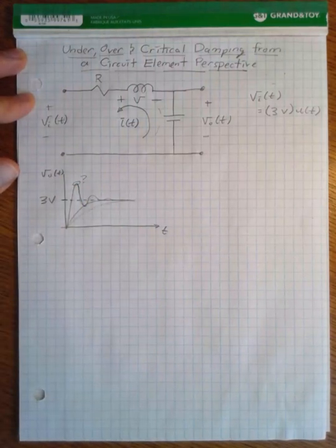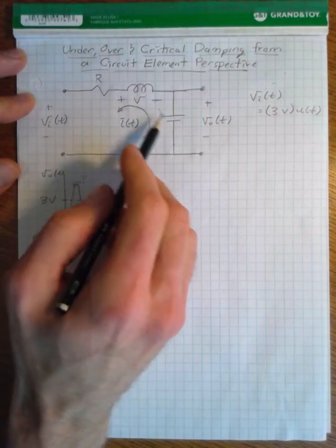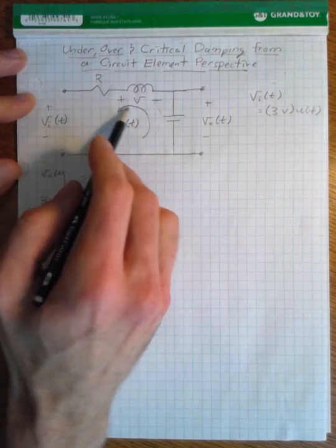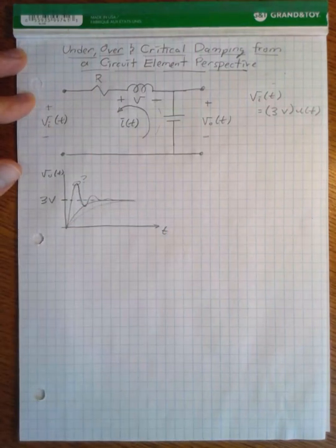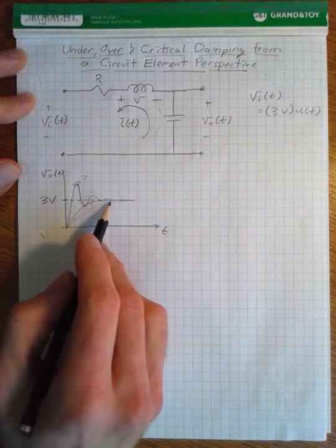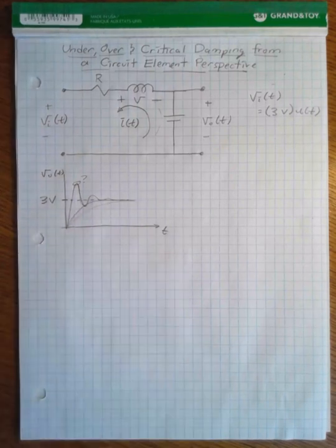So it actually steals energy from the circuit. And so the capacitor and the inductor are kind of exchanging energy back and forth, but every time they do that, current has to flow through the resistor, and there's a little bit less energy to share back and forth. And so that's what causes the exponential decay of the amplitude.